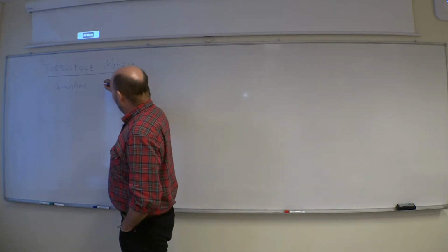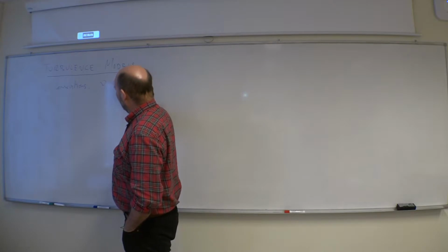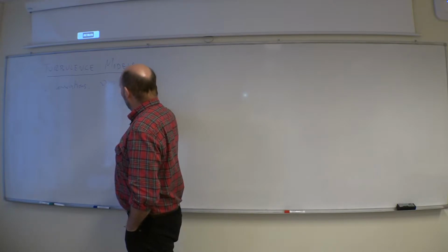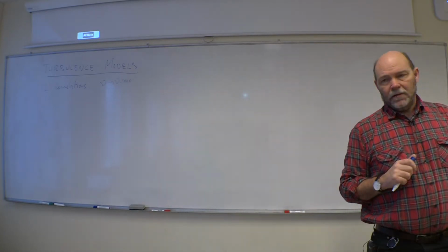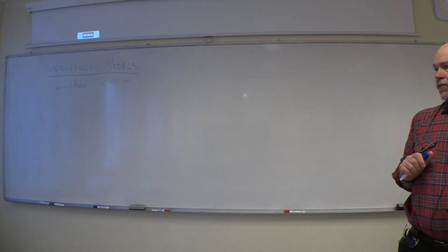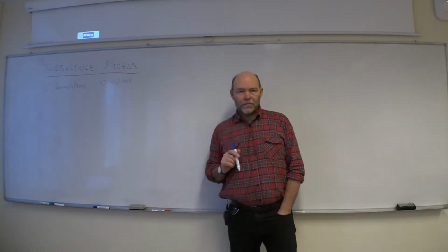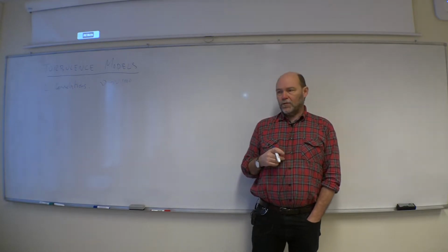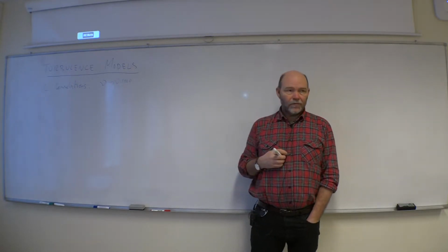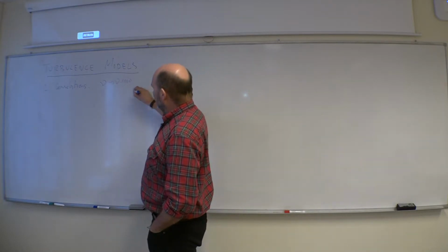Well, a very simple model will then be to say viscosity is now viscosity multiplied with a big number. That's a turbulence model. Then what you are actually doing is you are reducing the Reynolds number to something that becomes laminar, and then you have control. So it's a very bad model, but it works. But of course you are now simulating a totally different fluid than what you were thinking. So very bad model.